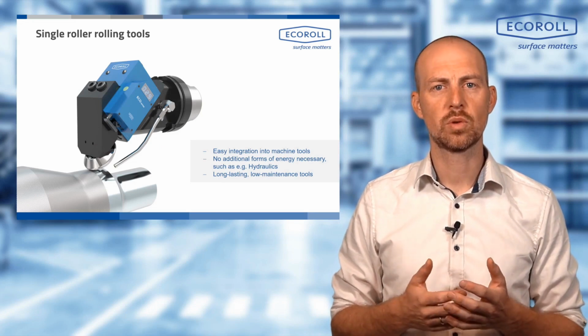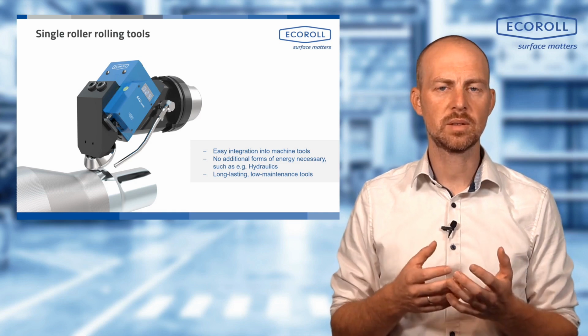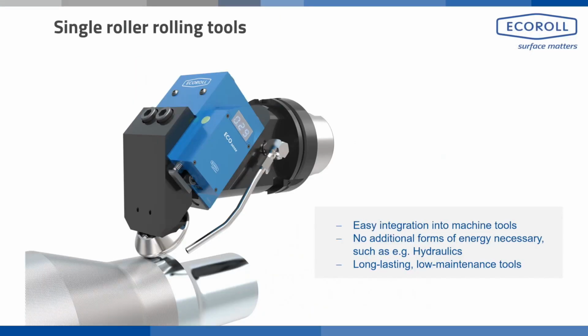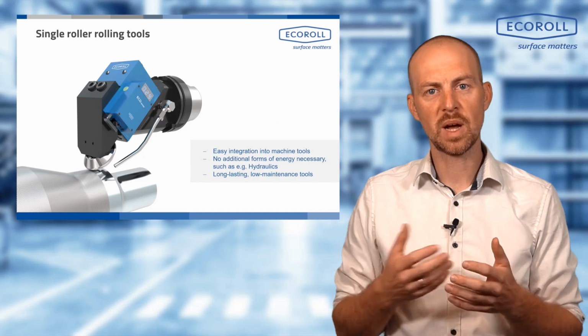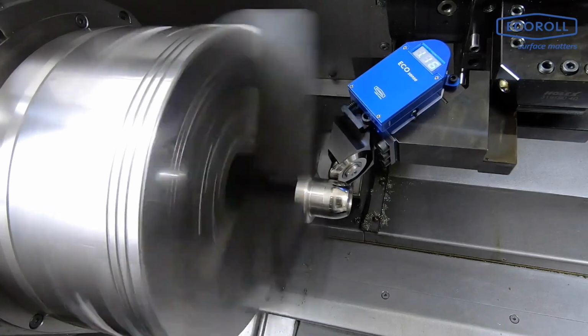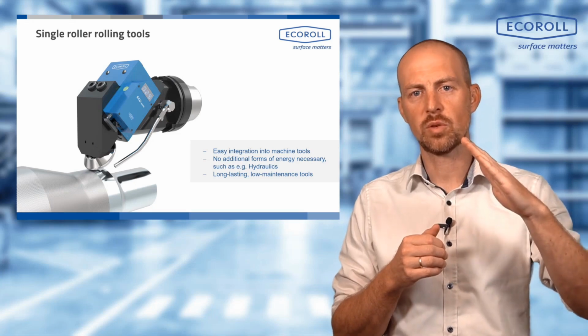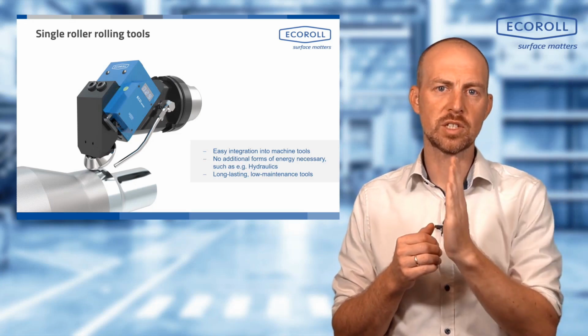For processing curved arches and radii, we use single roll mechanical tools. In this type of tool, a rolling roll is held axially and radially, and it can then be precisely controlled over the surface. This means that through my NC code, I can define the rolling force at each individual point. I can change my feed rate and thereby influence the rolling force. Why does it work? Because these tools are equipped with leaf springs. I have the rolling roller installed at an angle of 45 degrees. This rolling roll at 45 degrees allows me to process a wrapping angle of 90 degrees.